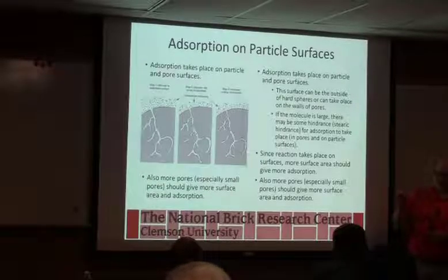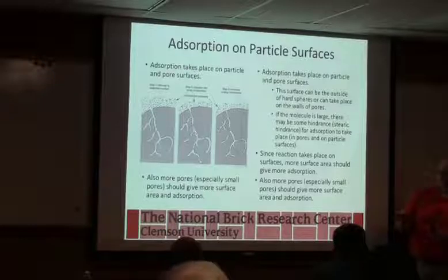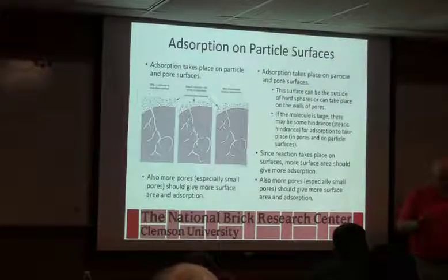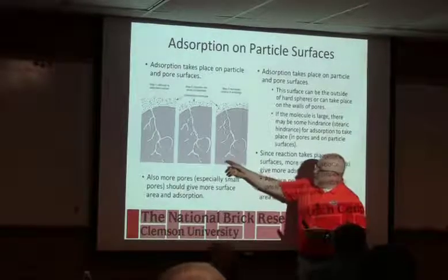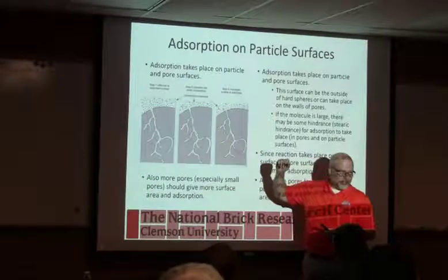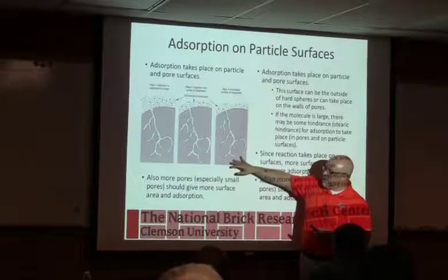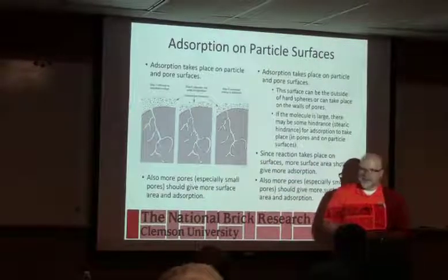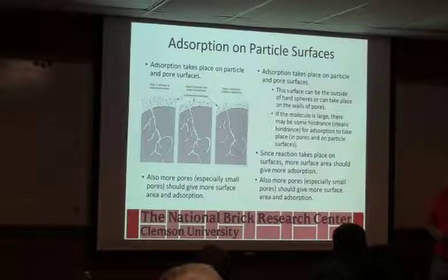The problem is you don't want something that's so soft that it crushes in your scrubber. You want something that stays together. So you're trying to balance strength with porosity when you buy that scrubber reagent. They're now making some synthetic ones in Germany that have a huge surface area, and they're very effective. I think some of them incorporate some activated carbon. Probably if we ended up having to control mercury, we might have to start buying that stuff. But we'd have to see.